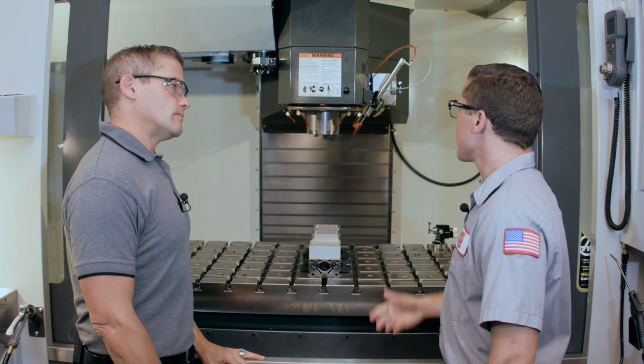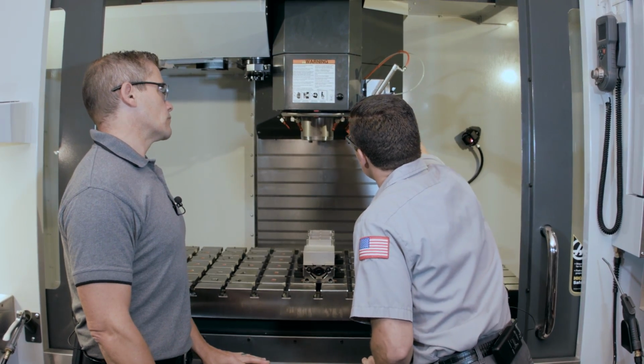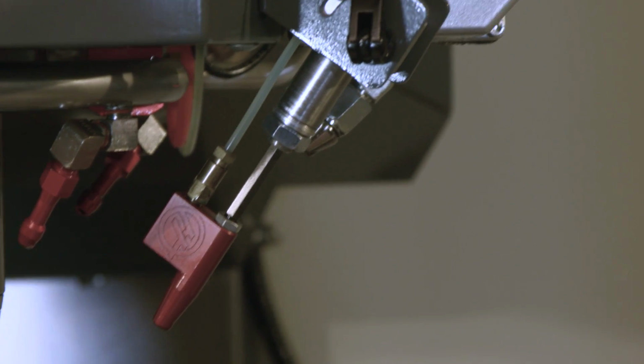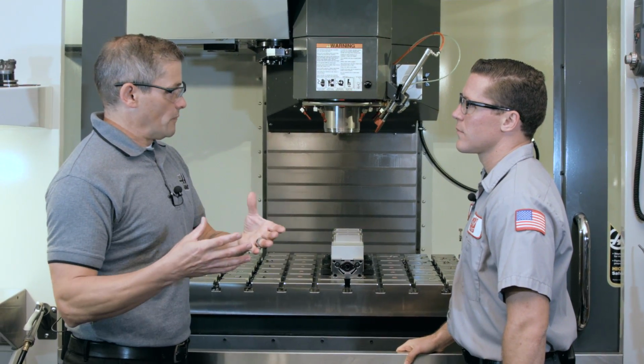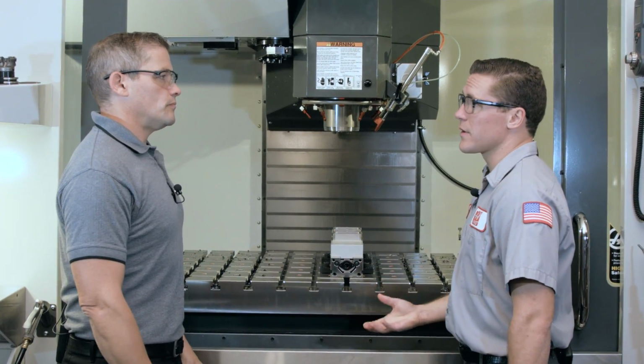Now, MQL piggybacks on top of the auto air gun option, right? Right, it just gets added on. So I do need to have AAG installed in order to add MQL to it. Yeah, so here we have our auto air gun body. Attached to that is our MQL nozzle with our oil supply line running to the reservoir on the side of the machine. So that means I can use it as an auto air gun, or I can use it as an MQL system, and it also doesn't interfere with my regular flood coolant system. Yeah, you don't have to completely convert to using MQL. Just use MQL wherever that approach makes sense and switch back to using flood coolant wherever that works.